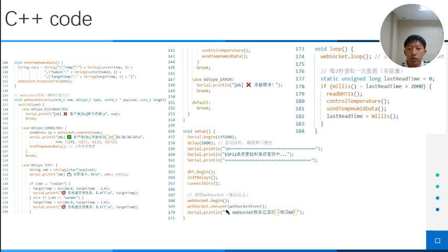Specifically, the code receives control instructions from the cloud through the ESP32 code module through the serial ports, such as target temperature, cooling or heating mode switching instruction, and controlling sensor collection frequency, adjusting the collection interval of the DHT11 sensor according to the received instruction.